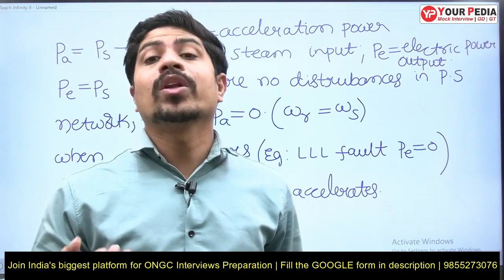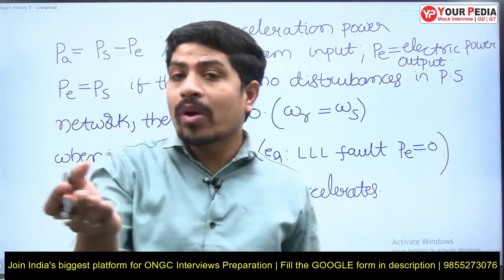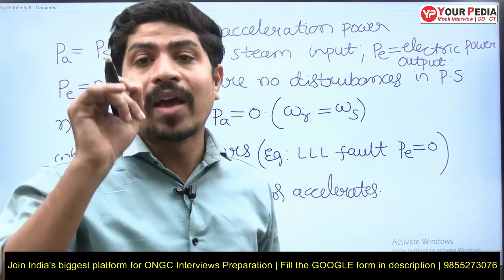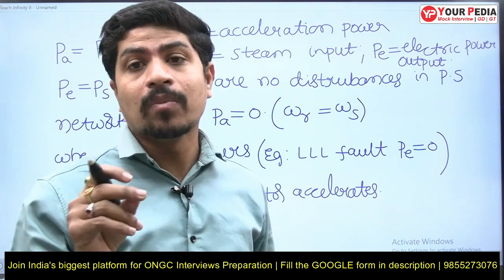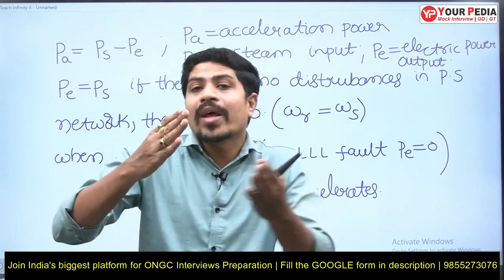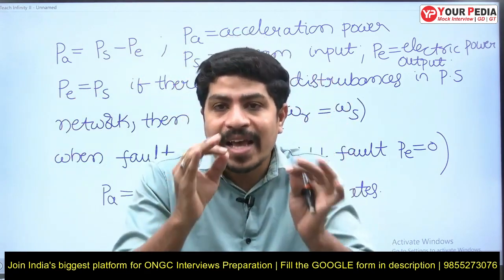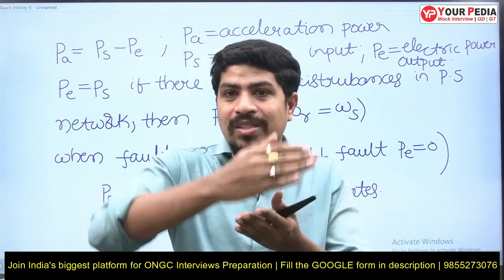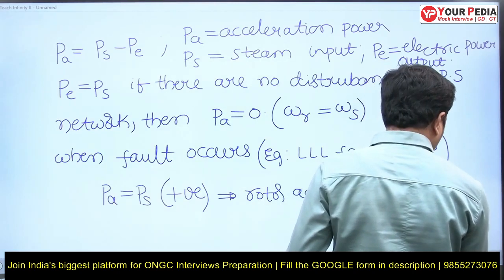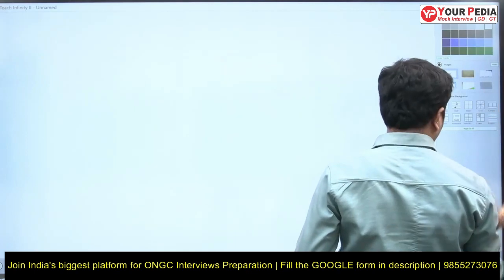From the equilibrium criteria we know that if the acceleration is more, it has to find more deceleration area. If that much deceleration area is not available, then the machine, or system, will become unstable. Do we want more acceleration or less acceleration? We always want less acceleration. If the acceleration is more, I'll draw that equilibrium criteria diagram also. Yes, I'm drawing here.